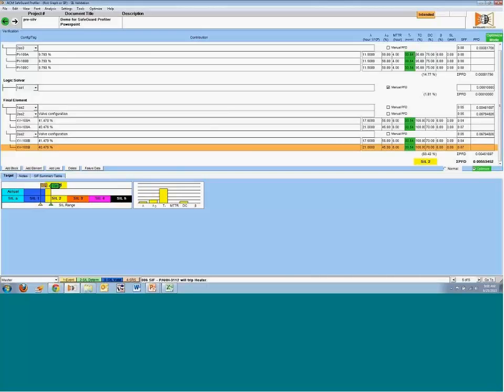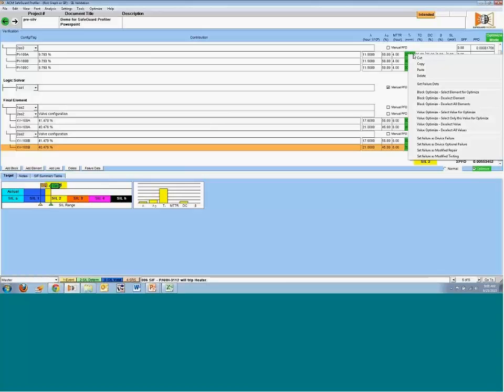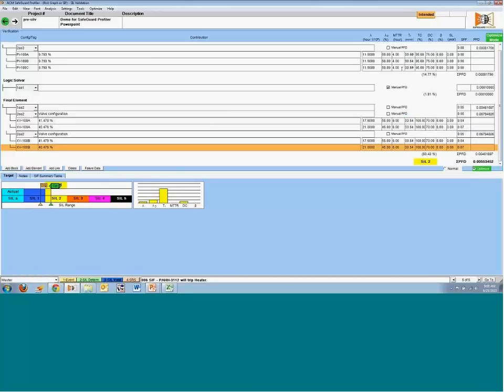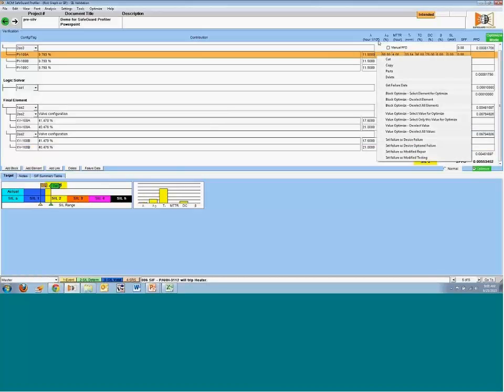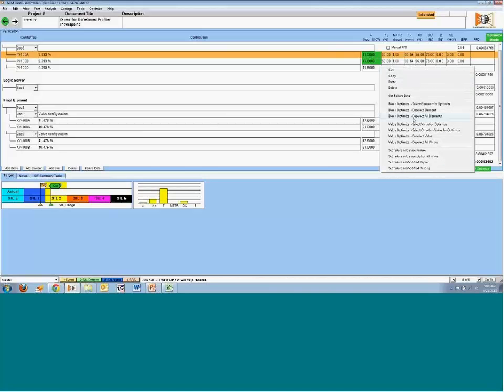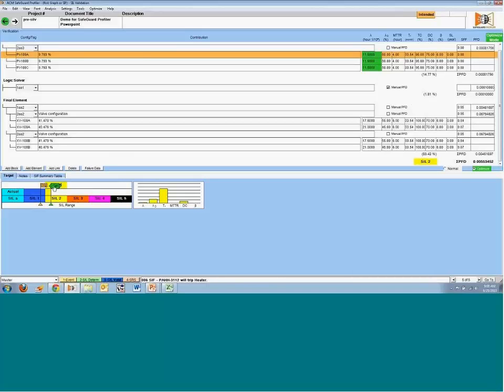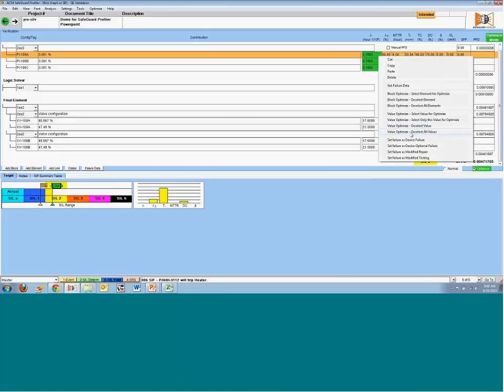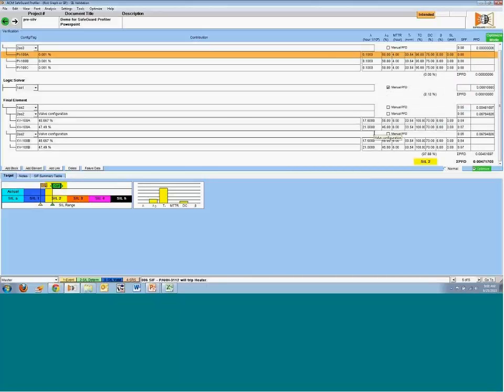As I mentioned earlier, you can actually change this equation based on any value. I'm going to deselect them here. If I just want to look at what type of failure rates for the sensors, so maybe I want to instead find a different sensor at this current rating. What if I wanted to bring that up further? Well, I need a really low failure rate in order to just get a SIL 2. So once again, you can pivot that equation based on any of these values as long as they're within the same column. The laws of mathematics say that it has to be in the same column.